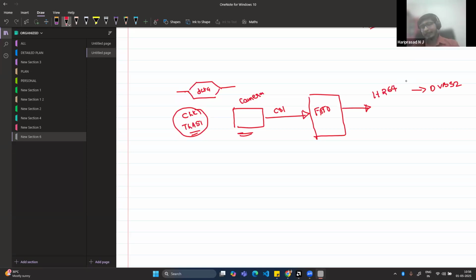Ideally it is sensing earth parameters, like temperature or geological survey. You can think of this camera as some application. Because of confidentiality, I may not be able to reveal where exactly I'm using it. So some application getting the data, I have to do H264 encoding, and through DVB-S2, I have to transmit to the ground station.